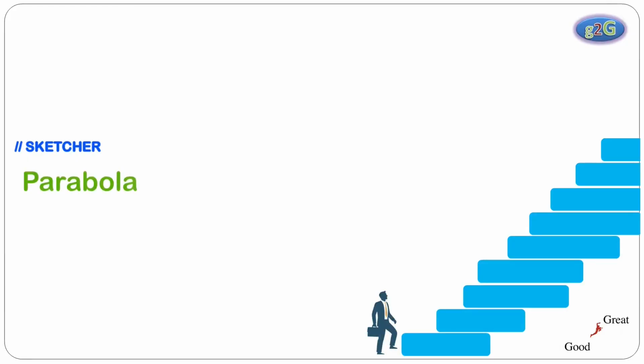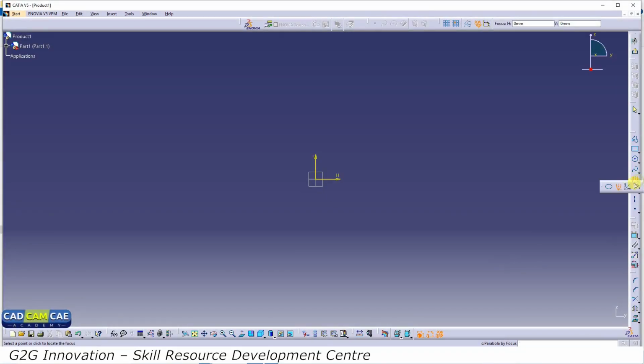So the next command is parabola by focus. In order to draw a parabola, we need to define 2 points. One is the focus and second is vertex. Let's see how to draw a parabola. Click on the command of parabola by focus.